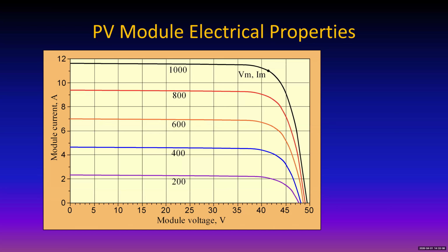And fortunately, the technology is out there so that the inverters that convert, the charge controllers, and any of the other electronics that these modules feed into can be designed to operate the modules at their maximum power point. And why would you not want to do that, since the power they're getting from the sun is free anyway? The only reason you wouldn't want to do that would be if there's nowhere for that power to go. And obviously, if you're operating at a certain power level, then that power has to be used somewhere.